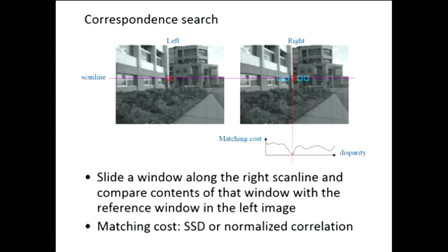For example, the Kinect system is actually doing stereo using a projected image and a measured image. And the intensities of the projected image will not really match the intensities of the measured image. And so they use normalized cross correlation. The Kinect is projecting the image in infrared, so that's why you can't see it. It's projecting a random dot pattern, and that's the basis for its stereo. The Kinect is a sensor that's used for robotics and used for Xbox games.